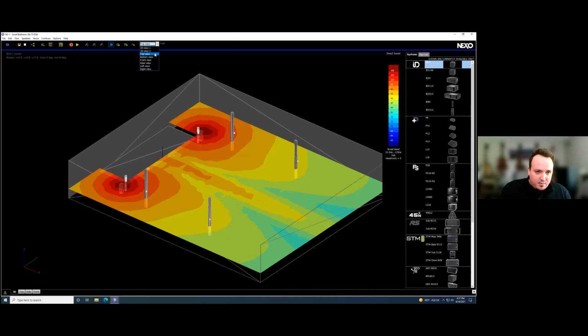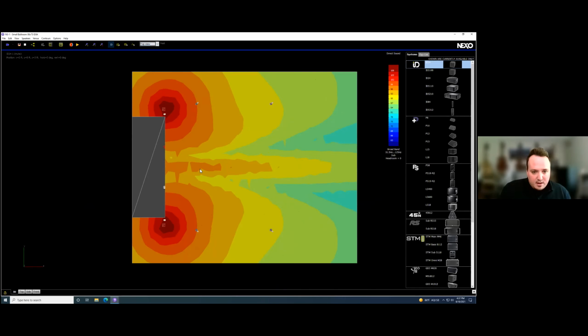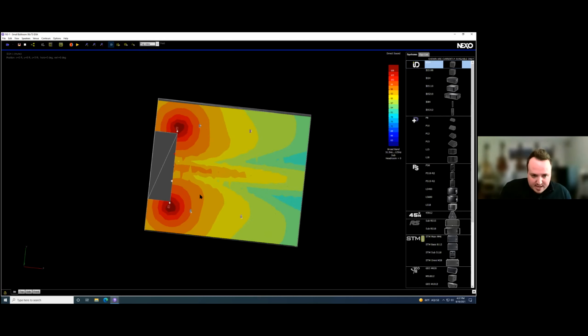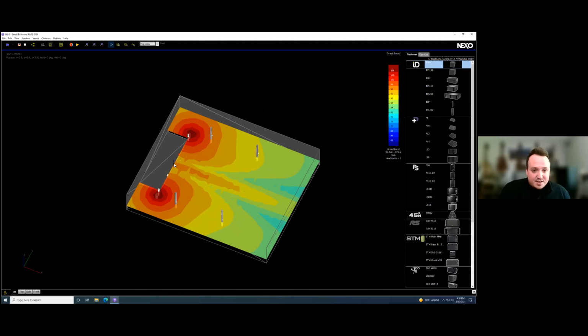So yeah, jumping over, looking at subwoofers. Obviously, with a left-right subwoofer scenario, we are going to get a lot of lobing going on. But hey, it's a portable application, so we're going to put the speakers where they make the most sense for a lot of different scenarios. We could tight pack them under the stage, but maybe that stage is solid. Maybe it's not a stage at all. Maybe they're going to stand on the floor.